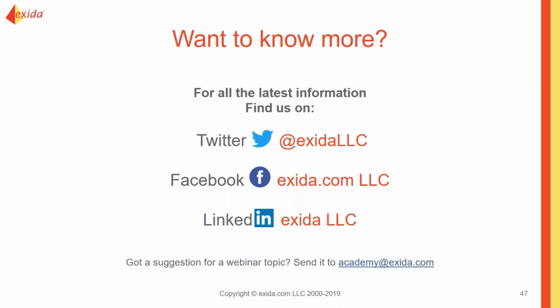OSHA does not say you specifically have to use IEC 61508. However, OSHA does say you need to be using best engineering and common engineering practices. In the world, IEC 61508 is considered the common and best engineering practices. So no, it is not mandatory or a requirement, but if you get yourself into an accident or a situation or litigation, they could and will ask you why you weren't using the best engineering practices if you are supposedly following OSHA.